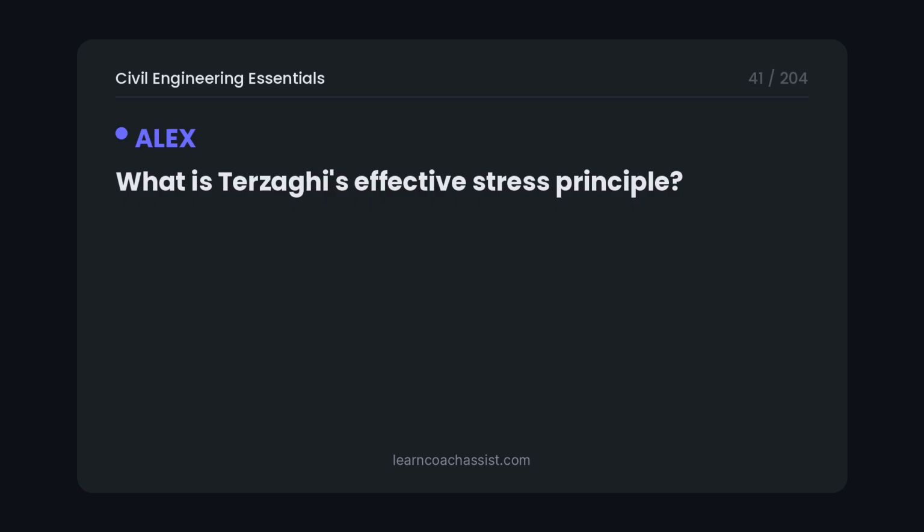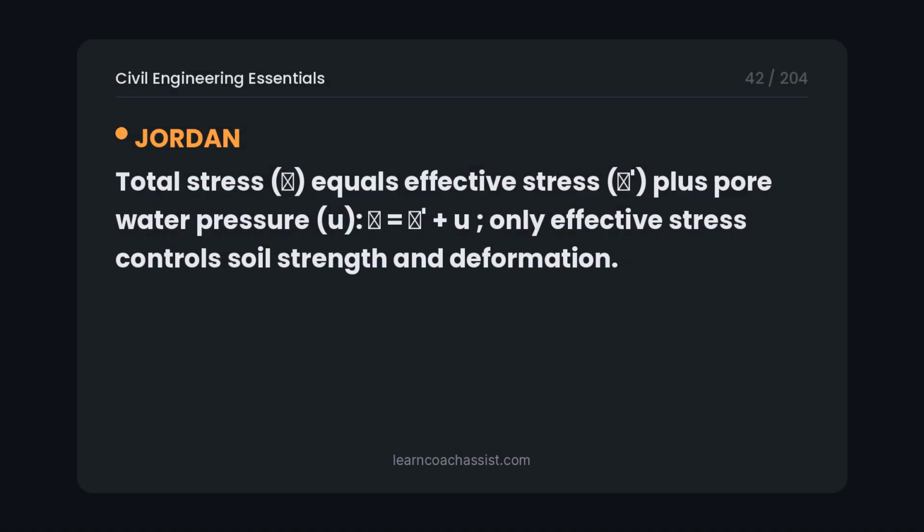What is Terzaghi's effective stress principle? Total stress, sigma, equals effective stress, sigma prime, plus pore water pressure, u: sigma equals sigma prime plus u. Only effective stress controls soil strength and deformation.